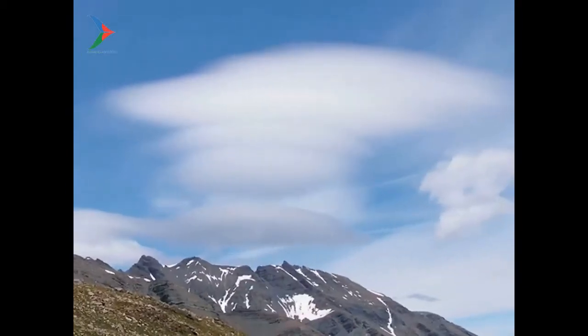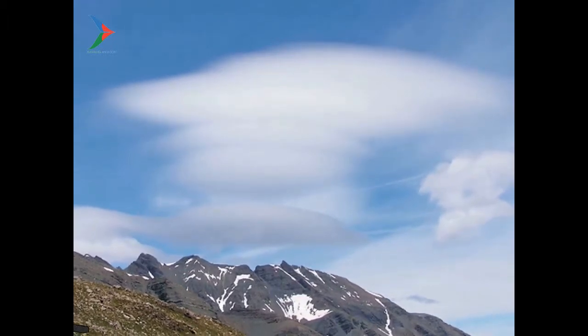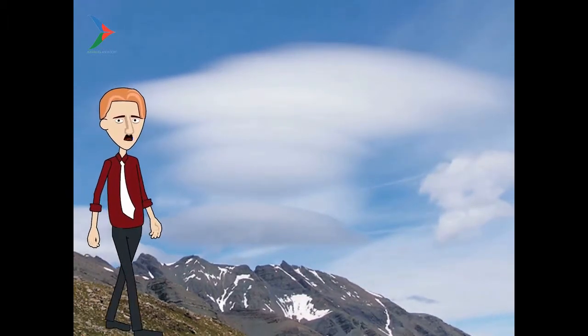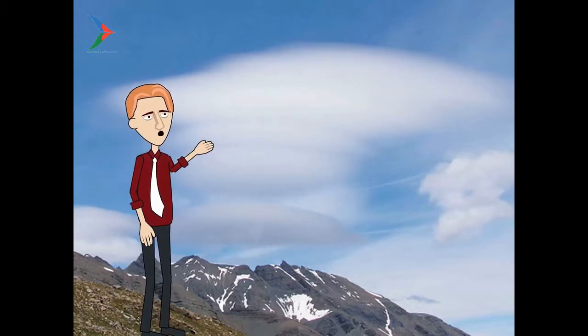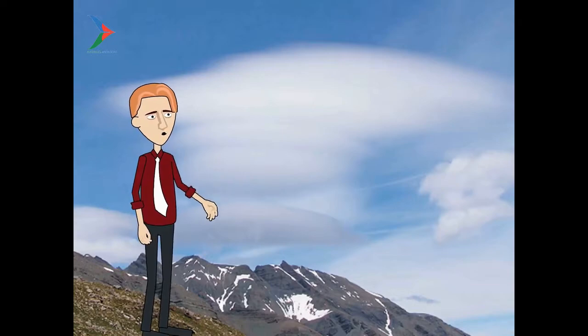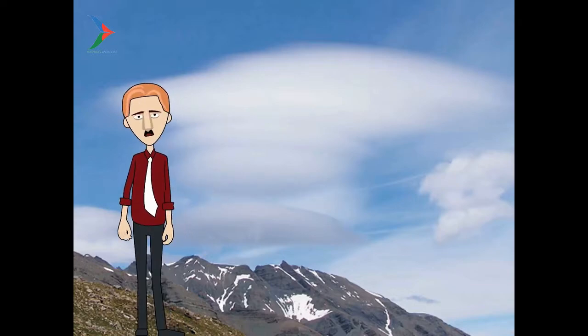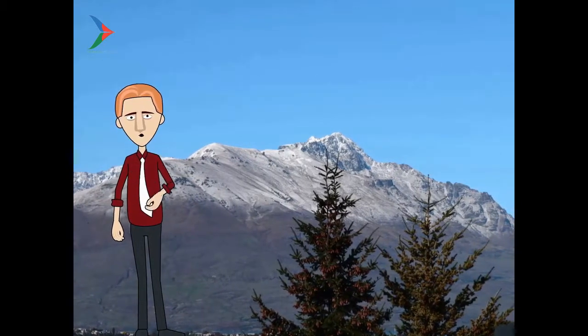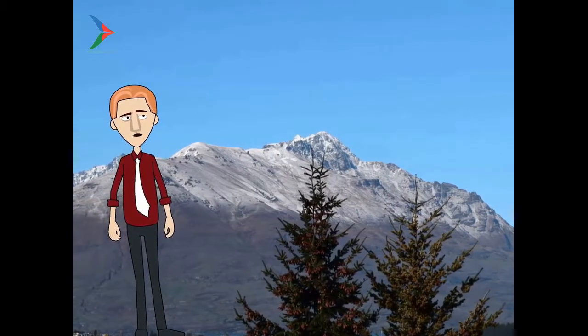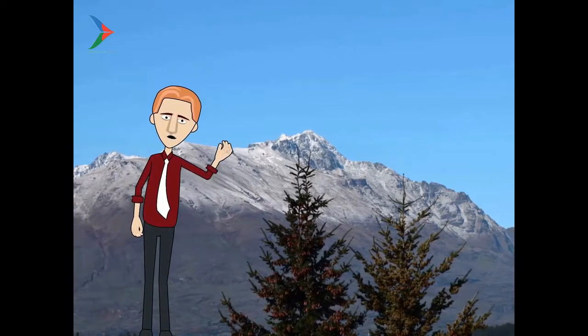Violent turbulence will also be found in the up and down drafts associated with lenticular clouds. Pilots must be especially cautious when flying near or around mountain waves. Many varieties of turbulence appear in these wave patterns. Keep in mind that mountain waves can and do form in dry air. The only problem is, you can't see them. In other words, telltale lenticular clouds are not visible.